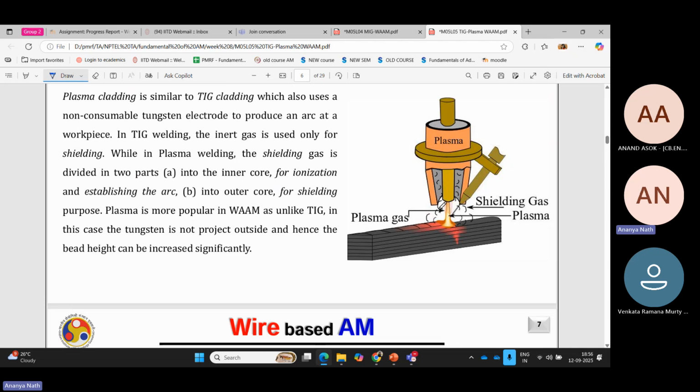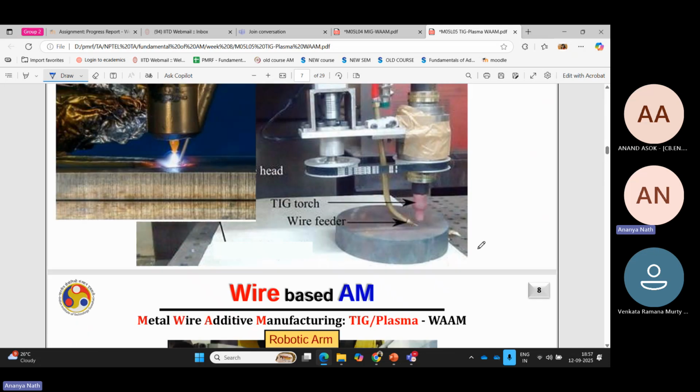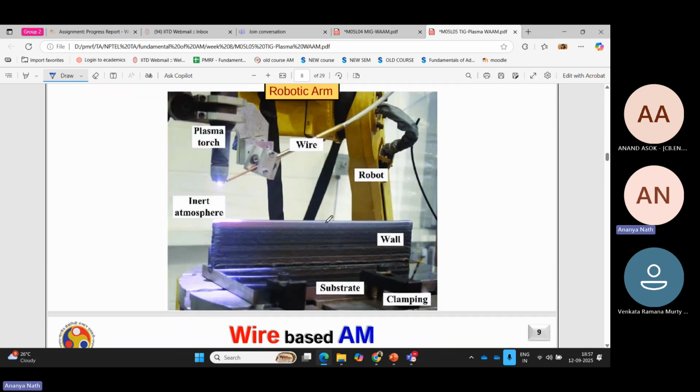There's a shielding gas. The shielding gas also maintains the melt pool shape. It also avoids contamination, moisture entrapment, porosity and oxidation. But due to the gas feeding, we also get some gas entrapment and porosity, but that is not very much. That can be avoided as well. So it's almost the same thing. In the same way you can print, only the wire is coming from another source.